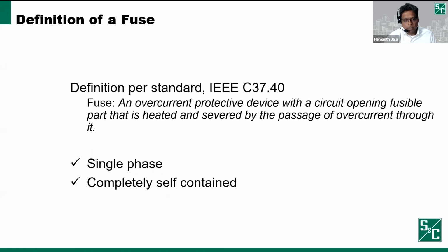What I do want you to take away from this slide is there are 2 key things when it comes to fuses. The first one is it's a single phase device. You apply fuses per phase, and you use fuses on a single phase basis. The second one is fuses are completely self-contained. What we mean by that is the fuses have the sensing and interrupting element combined into one little package.